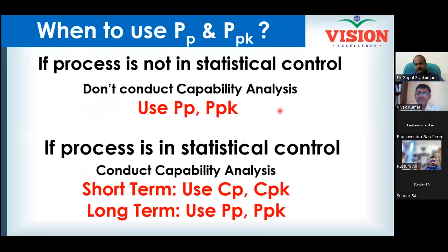Whenever your process is not in statistical control, it is not advisable to conduct any capability study. If you have not attended the training program, there is no point of conducting the certification exam for you. Am I correct or not? You have not attended the training program, and what is the point of assessing? Similarly, if your process is not even in a state of statistical control, better avoid conducting the capability study. It is going to give no meaning. But if at all you are forced, then just look at Ppk, not other things. At least you get to know a closer picture.